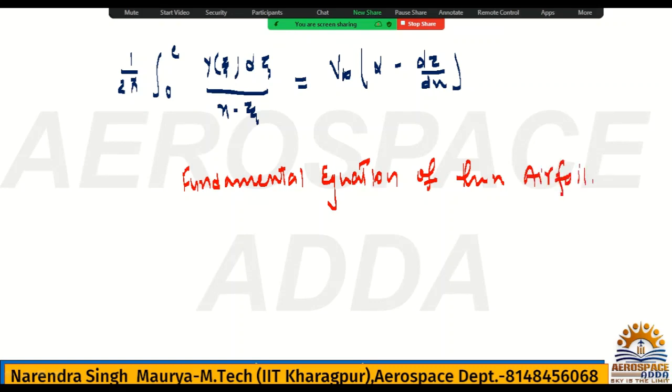For different types of airfoil you can take different conditions. For the flat plate, the value of dz by dx will be 0. Similarly you can do the calculation for cambered airfoil and symmetric airfoil also. So this is the general form, and from here you can get the final equation for whatever type of airfoil you want, cambered, thin, or flat plate. This was the fundamental equation we had seen in the last class.